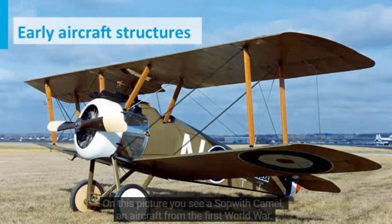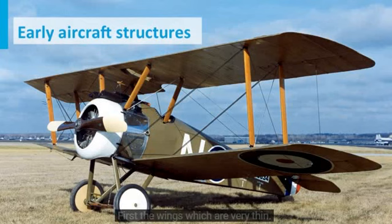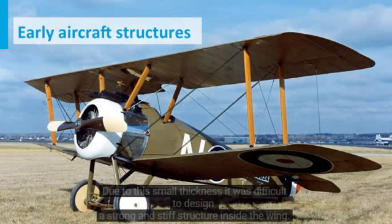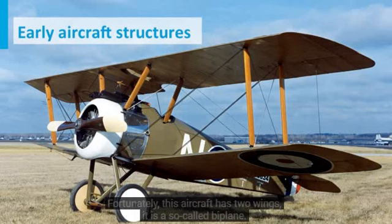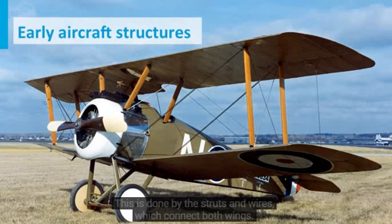On this picture, you see a Sopwith Camel, an aircraft from the First World War. Looking at this aircraft, we can see a number of typical features. First, the wings, which are very thin. Due to this small thickness, it was very difficult to design a strong and stiff structure inside the wing. Fortunately, this aircraft has 2 wings. It is a so-called biplane. Both wings support each other and provide extra strength and stiffness. This is done by the struts and wires, which connect both wings.